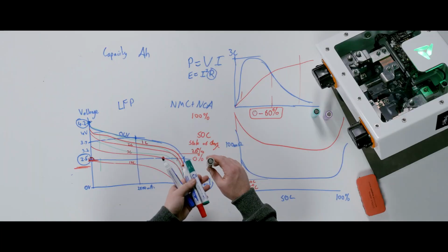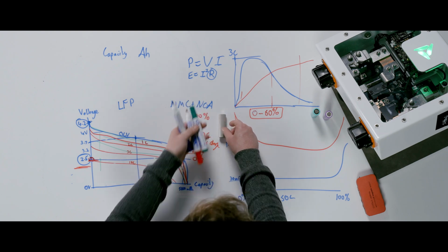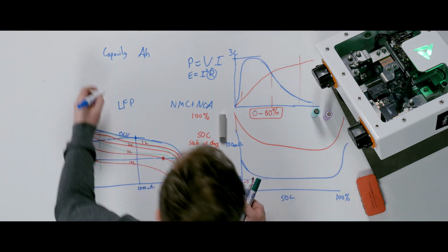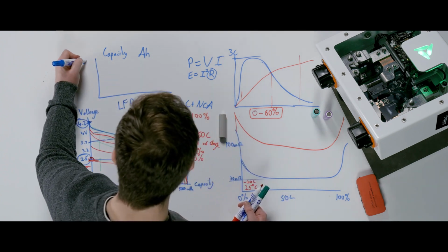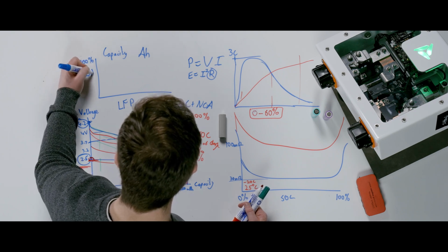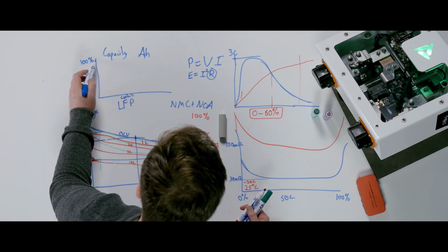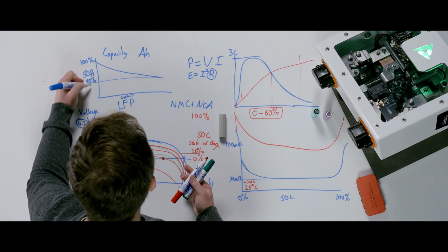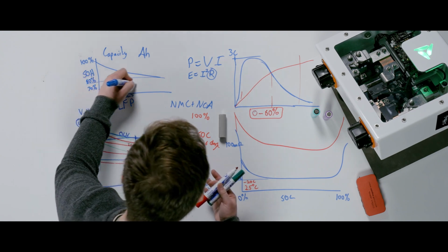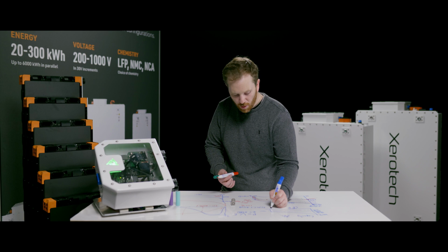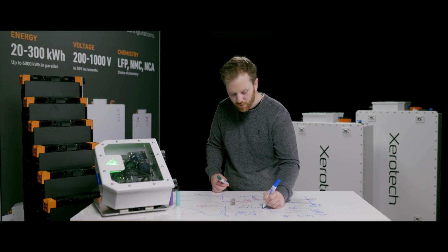So when you charge and discharge a battery up and down constantly, you don't end up with the same amount of power after each cycle. So what we defined before as 100% SOH, state of health, over time, as we do more and more cycles, starts to decrease and drop off. And we say a battery is at end of life when it reaches 80% SOH. Some manufacturers define it as 60, 70% SOH. And this could be for an NMC cell, could be 1,000 cycles, could be 2,000 cycles.